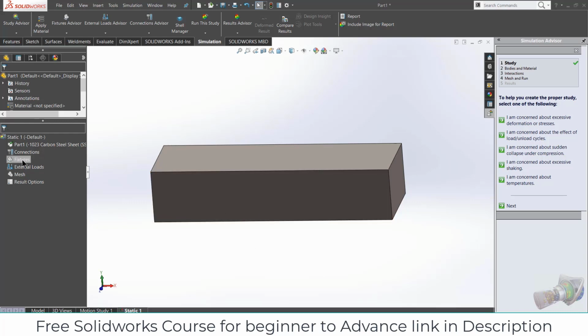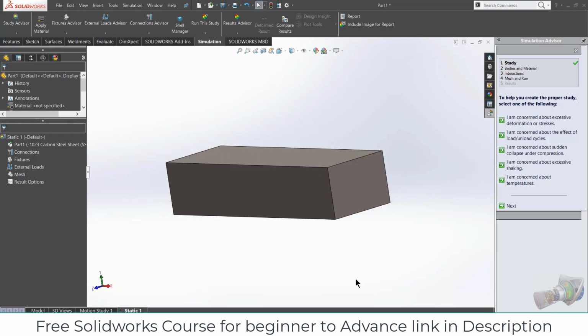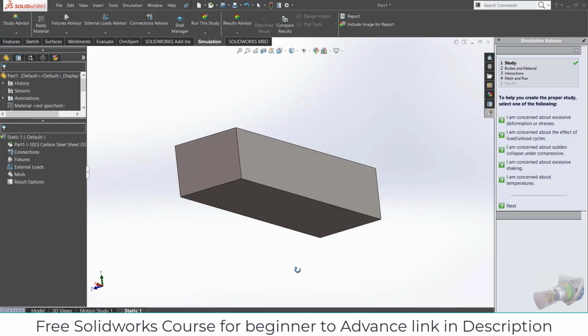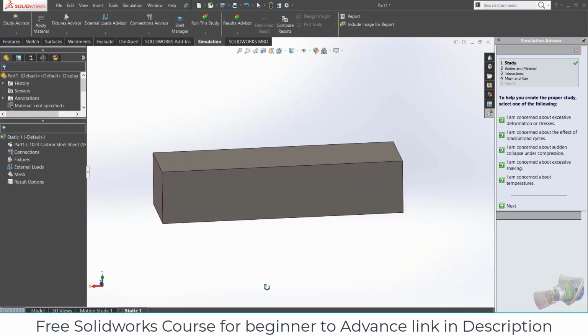Next thing is fixtures. So what is a fixture? As the name suggests, a fixture basically defines where it is fixed. In this video I am doing a cantilever simulation analysis. We know that in a cantilever one side is fixed and the other is free to move. So is any side fixed? The answer is no, because I haven't defined which side is fixed. So we can define it by using a fixture.